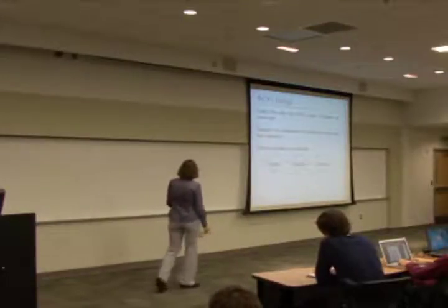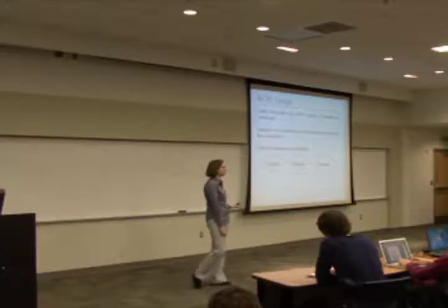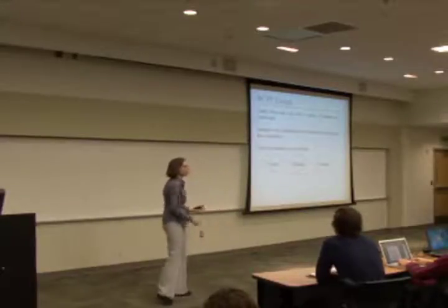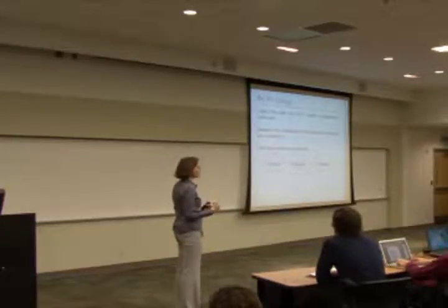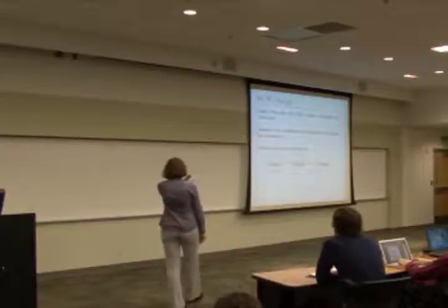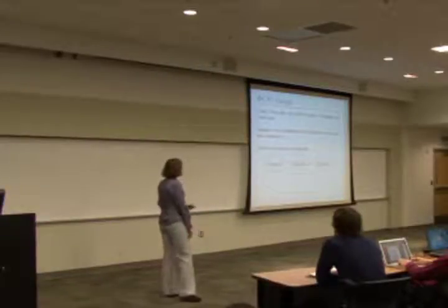Theoretically, you can do that at the end when you finish the execution, but you will see that when you have, let's say, branching or any jumps, that PC may change in between, so you really want to have that increased at the fetch state.